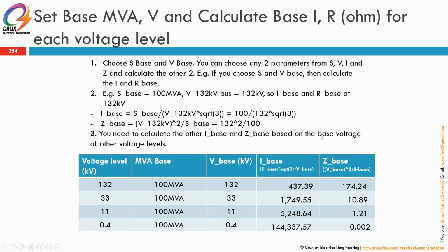So once you know this one, you get the hang of it lah. You just need to know how to do it for one voltage level. The other voltage levels are the same. But what you have to be careful about is the selection of the V base. Make sure it's the same lah, to make your life easier when doing all this calculation.